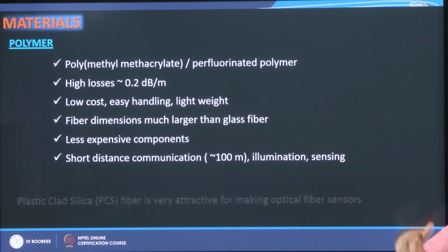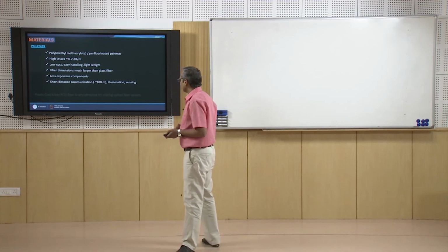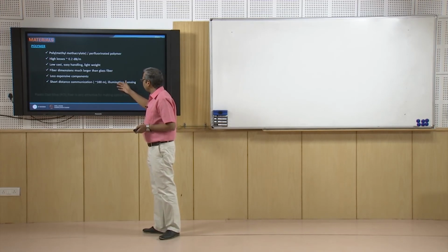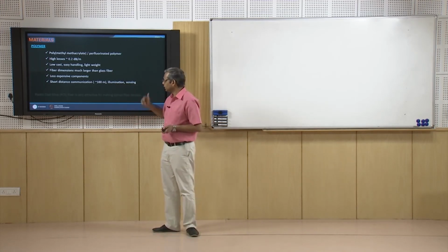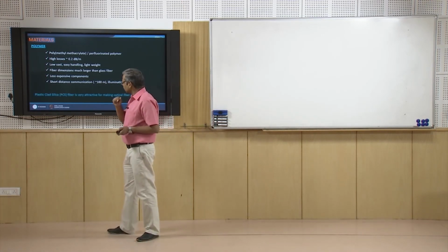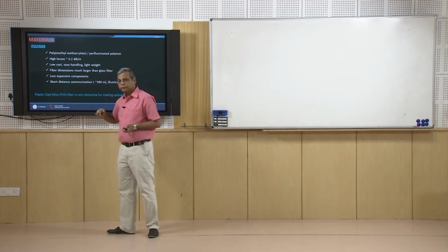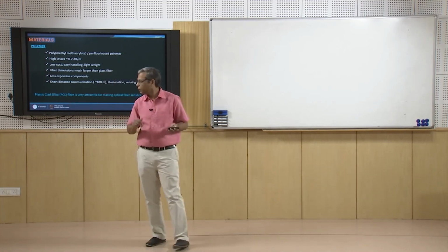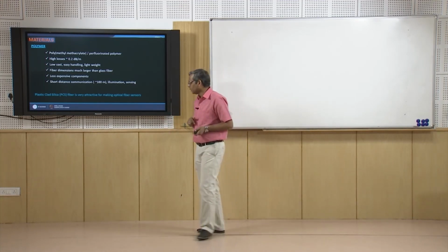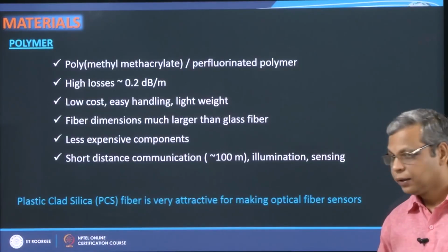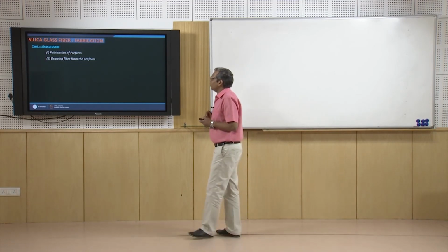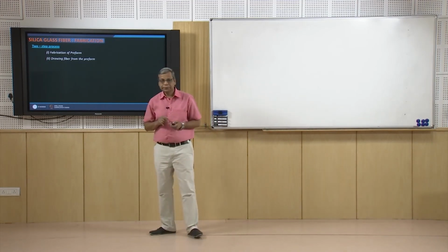So, we have different options. One option is that you make the cladding out of pure silica. Since the cladding is out of pure silica, here 1.46, the core should be using either of these. So, in the core you can dope germanium or aluminum or phosphorus or titanium to increase the refractive index, and the most widely used material is germanium. You usually dope germanium to have high refractive index in the core region.